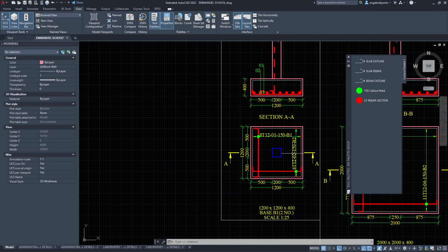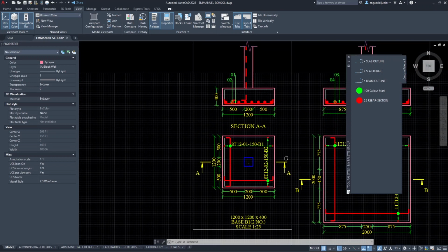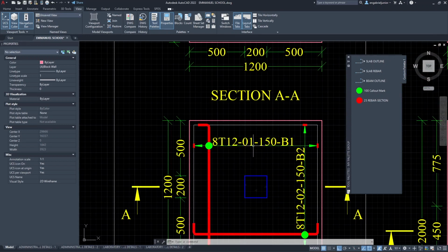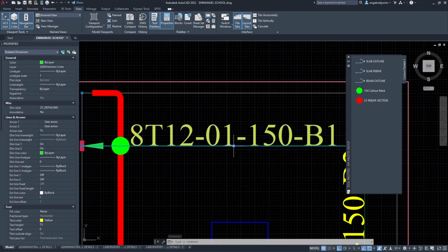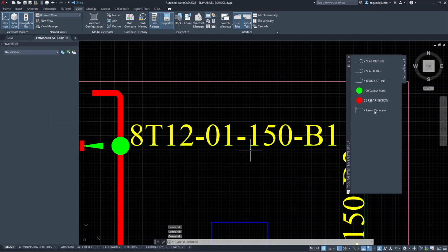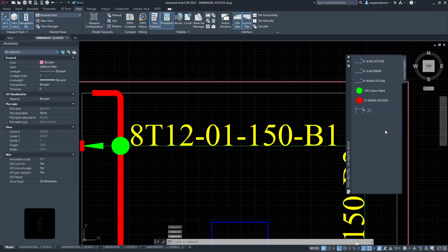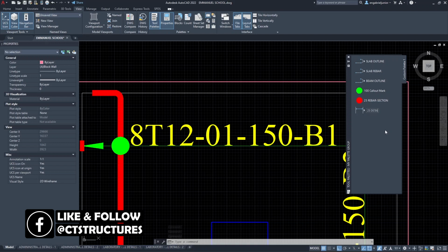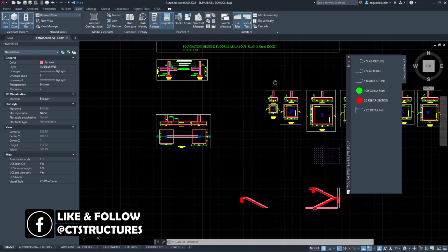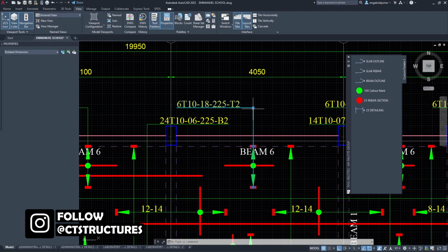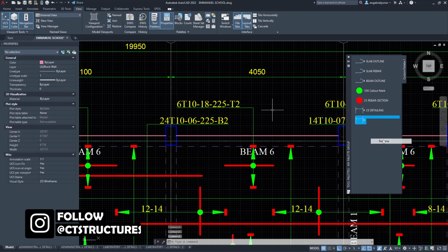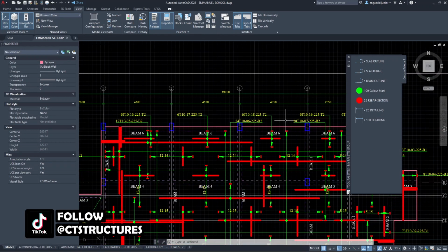So I can also go ahead and add perhaps also the dimensions or the detailing marks, something like this. So this is for scale 25. So I select it, click and drag, place it there. I rename it 25 detailing. Also go back to the slab, just do the same, select this one, right click, hold, drag, rename it 100 detailing, something like that.